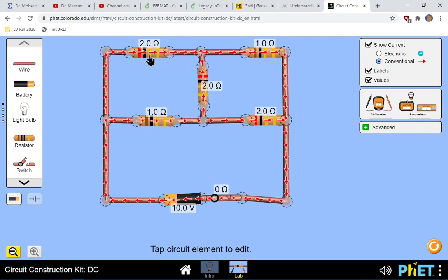If I play with the resistor here, at some value of resistance the electrical potential between these two points becomes 0, and no flow is going to occur. That's the basis of measurement of one of the four resistors that we have in the circuit.